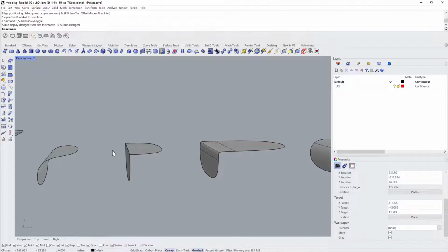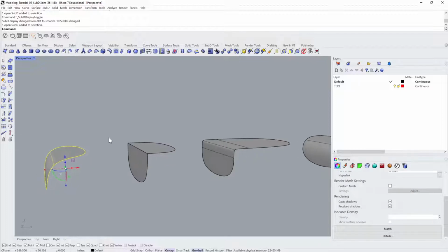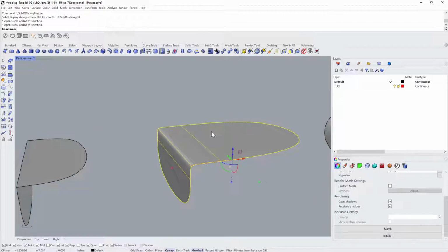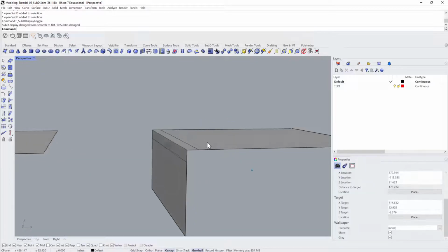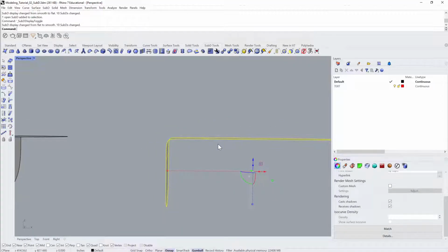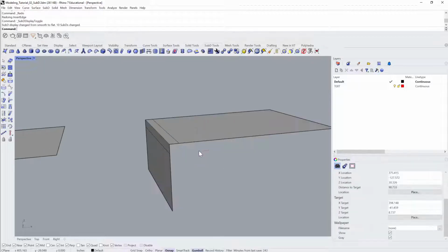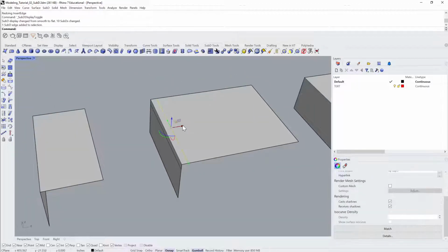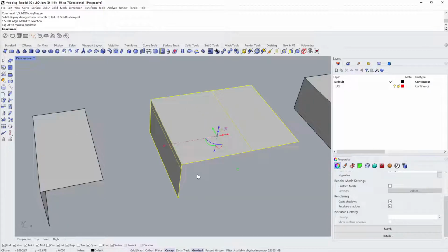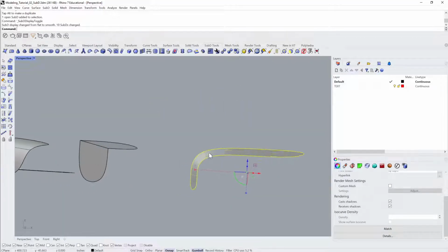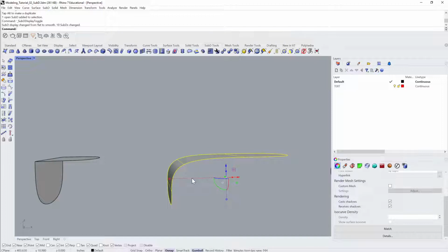So now you can see that we have these three transitions. We have this like very deep transition. We have a sharp transition because we're using a crease. And then with this one, we're inserting edges, right, and controlling that, so we get a curve that's more like just a rounded edge there, right? And as we, oops, let's go back. Let me undo that. Let's say that if I move these further away from that edge, then we go back to this more gentle transition.